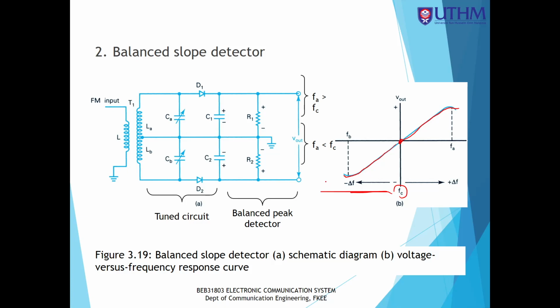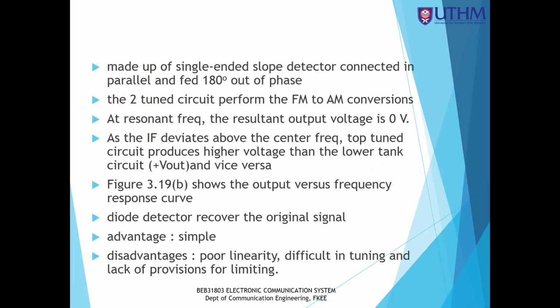So that means if the frequency becomes higher, it will produce positive output voltage. If the frequency becomes lower, it will produce negative output voltage. Okay, so at resonant frequency it will be 0. Resonant is the center of IF.